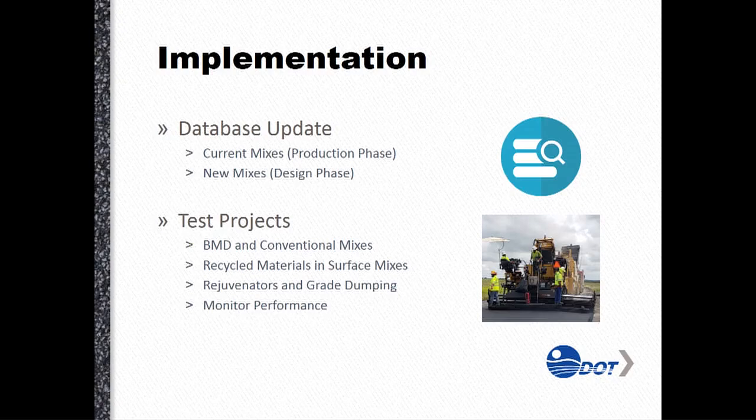And then we're starting to ask contractors to bring in mixes when they submit a new mix design, and we're going to start chasing those numbers and see what they look like. Test projects, we have 3 right now. We're putting side-by-side mixes on the ground: a balanced mix design and a conventional mix. We're putting them side by side.